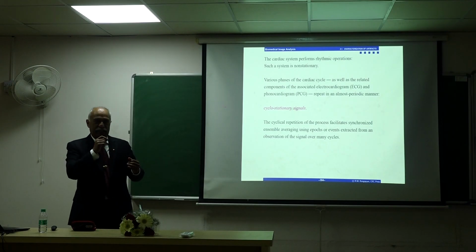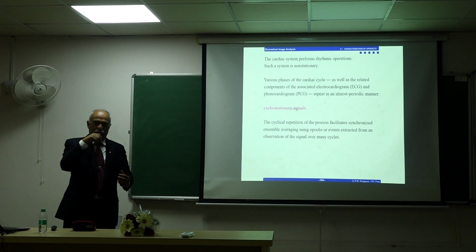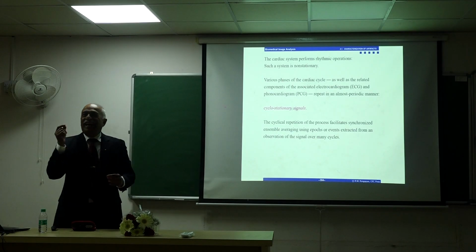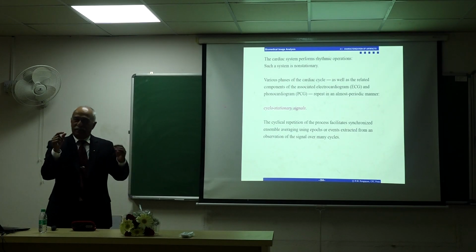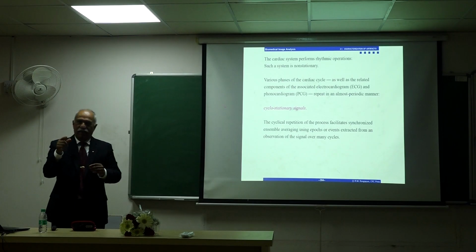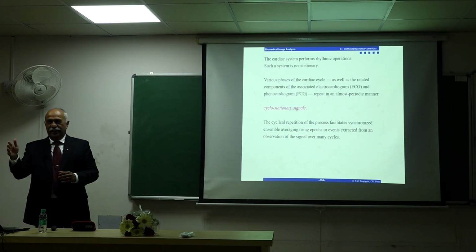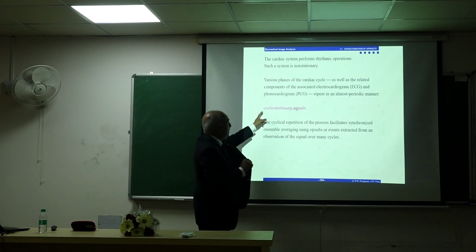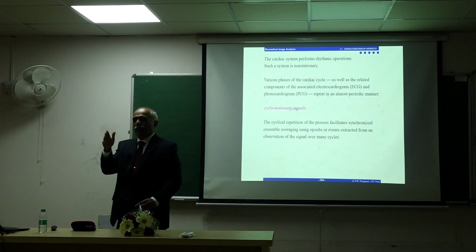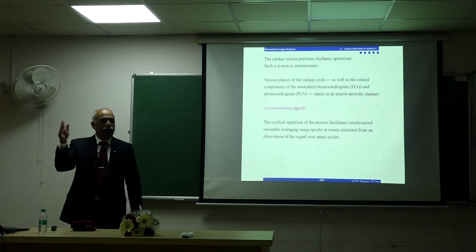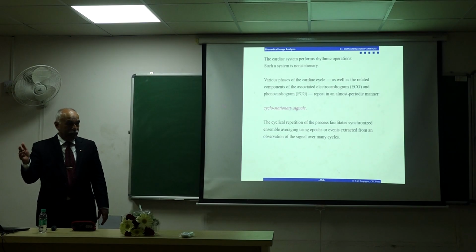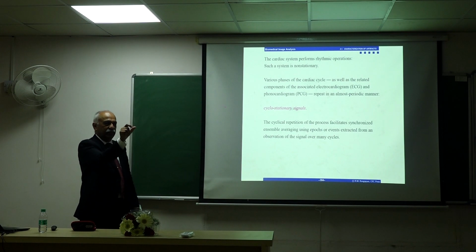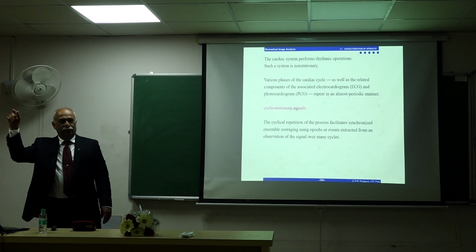But if you go within the heart, quite likely, if you put a microphone within the heart, you can do that. Not you, but trained people can do that. Then it is possible that those successive heart sounds, first heart sound is the same, second is the same. The murmur is random, so there could be variations. Then it's called cyclostationary. It is a cyclic process. The same thing happens every cycle or every beat. The heart rate could change, so you use the ECG as a trigger and say this much and that much from the next beat and that much should be the same.